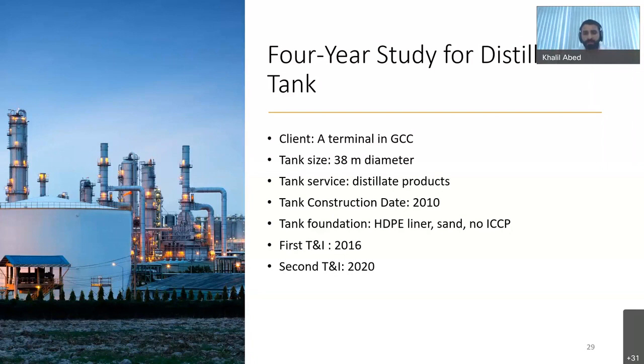The first case study is for a tank in a storage terminal in a GCC country. It's a 38 meter diameter tank constructed in 2010 on crushed stone ring wall, clean sand, HDPE, and with a release preventive barrier. The tank leaked after 6 years from construction date. So in 2016, the tank leaked, and it had to be taken out of service for inspection and repair. In 2020, the tank owner needed to change the service or the product stored in the tank, so they had to take the tank out of service, and they took this as an opportunity to check the floor status after implementing our solution in 2016.